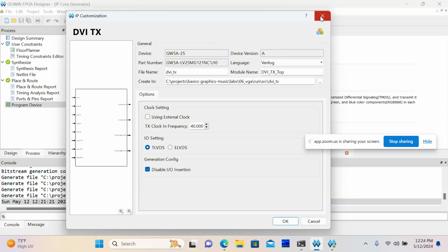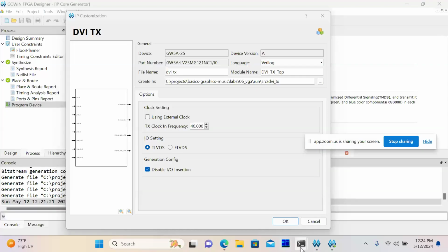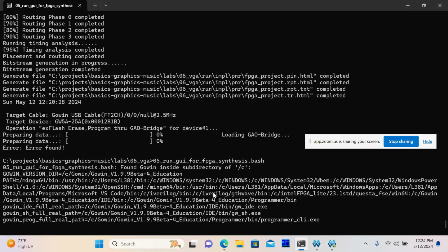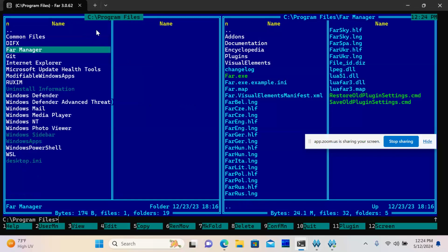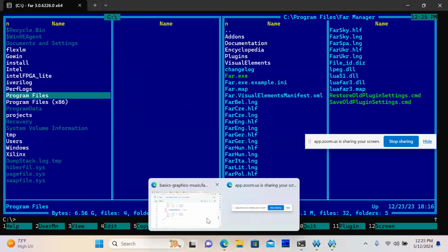So basically in Gowin, we have several files that determine how we map connections between physical pins and the pin representation in our design, in a Verilog design. Actually, I can show it in here.